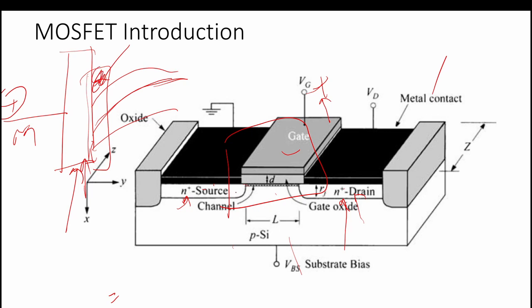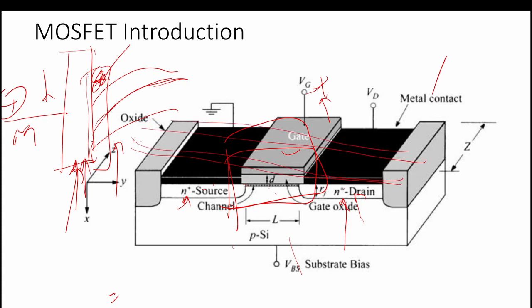This whole front part is this one. This is metal, this is oxide, and this is semiconductor. This front part I am showing you. If you take slices of this device like this, every time you will get the same thing. You have applied the positive bias, so everywhere the channel is created.